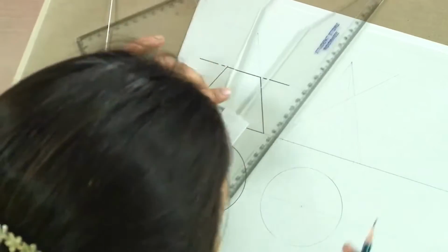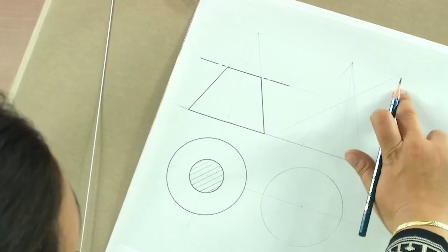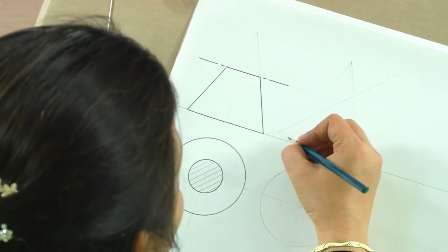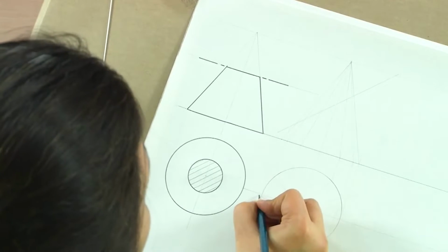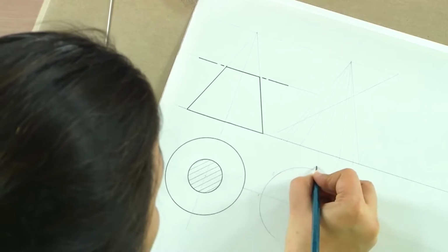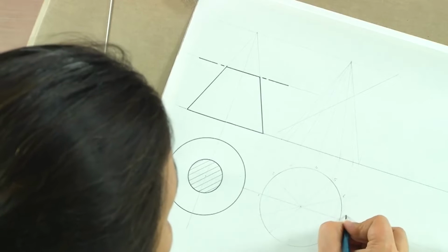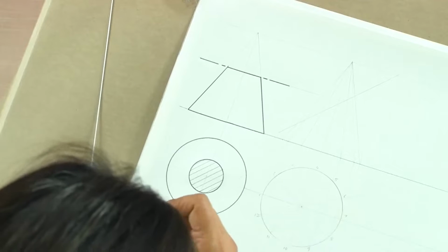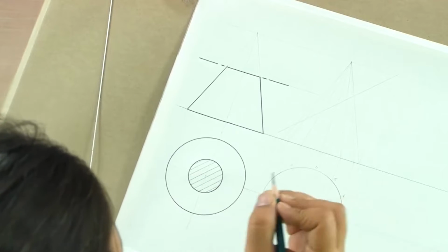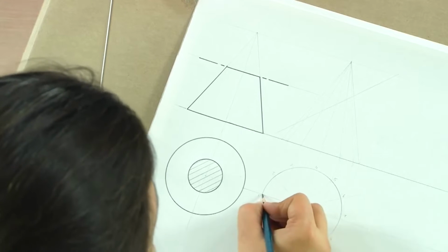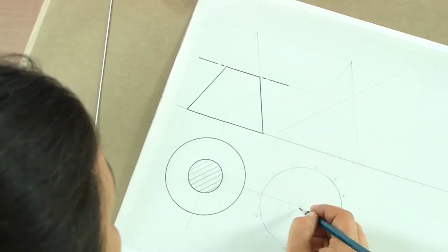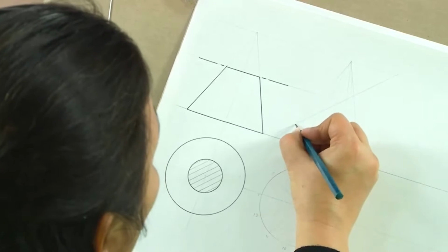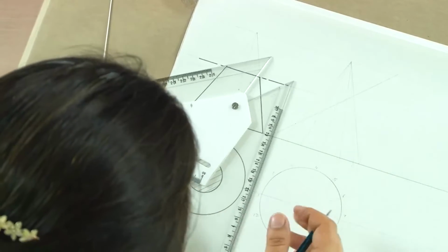So, now we have joined all these generator points to the apex, and wherever this plane cuts each of these generators is the point which we get here. I will just number these, so it is easier for us to locate the points. We have again divided the entire circle into 12 parts, and this is the apex O. Wherever the generator joining the apex and one of the points is cut, is the point which we will get. So, O1 is getting cut here.